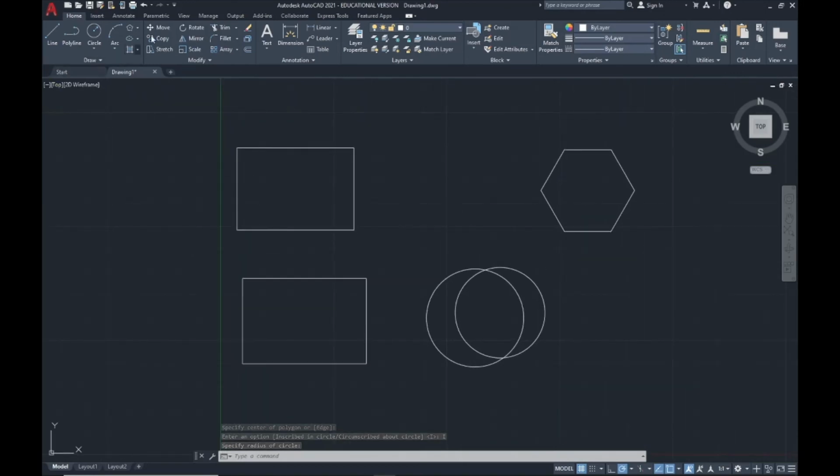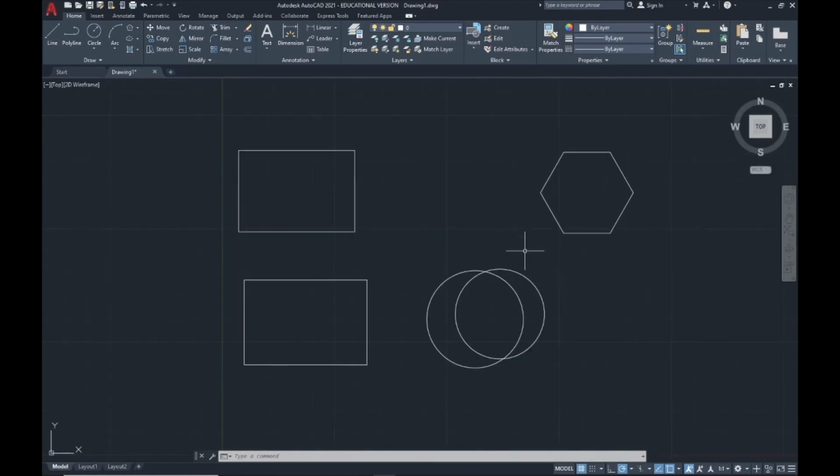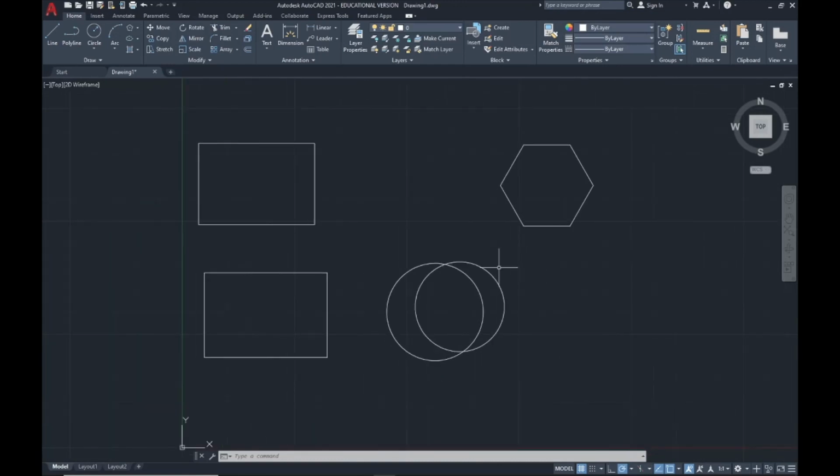So that's the way the draw panel works. You choose which geometry you want to draw, and then using the left clicker on your mouse, you draw either your lines, your rectangles, your circles, your arcs, etc. You draw that in your graphics window here on your screen. And you can zoom in or out, and you can pan, and you can select and delete as needed.